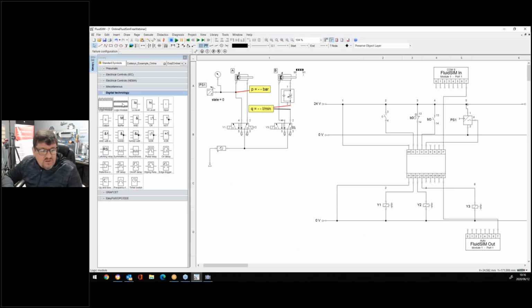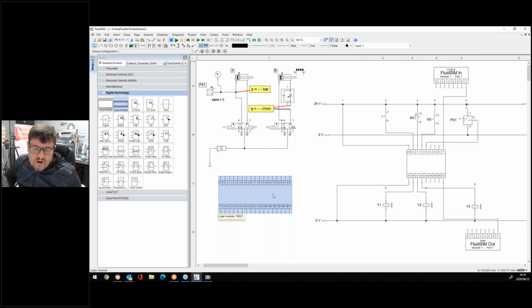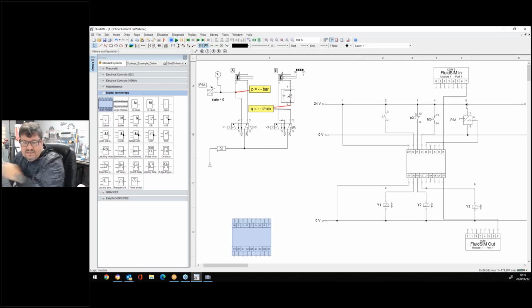I can click onto that one and drag it over to this side. Then you can also have a lot more, for example 16 inputs and 16 outputs. That means when you write a program that works with 16, that is a word input, that means 2 bytes. The same with the output bytes. You can utilize that, or you can use this one with the 8-bit, which is what I've used. Okay, I'm going to delete that part.